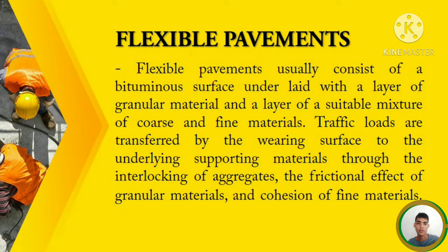Now, let's formally go to the specific. So, flexible pavements usually consist of a bituminous surface underlaid with a layer of granular material and a layer of a suitable mixture of coarse and fine materials. Traffic loads are transferred by the wearing surface to the underlying support materials through the interlocking of aggregates, the frictional effect of granular materials, and the cohesion of fine materials.